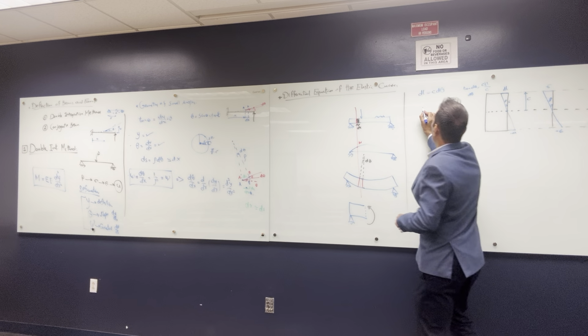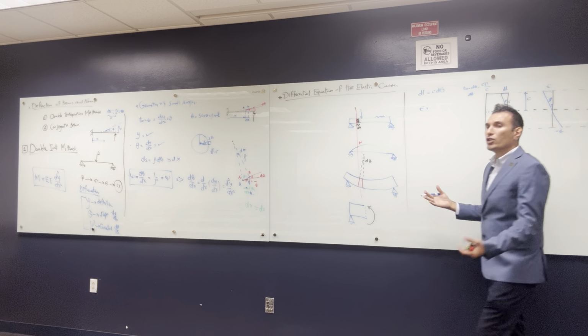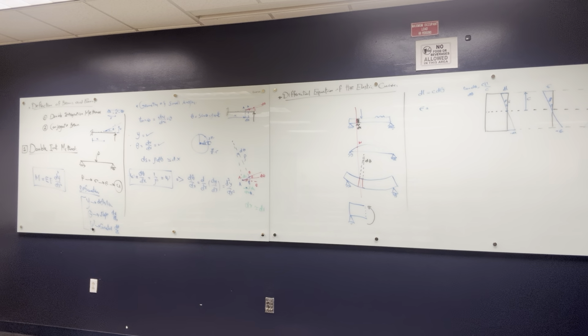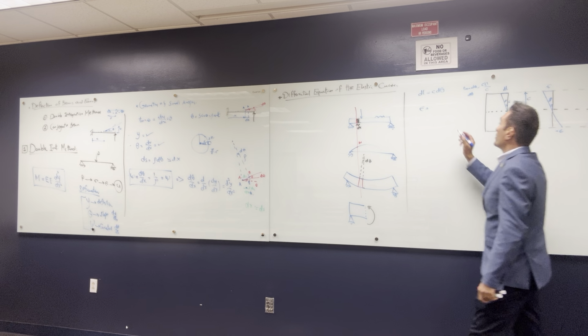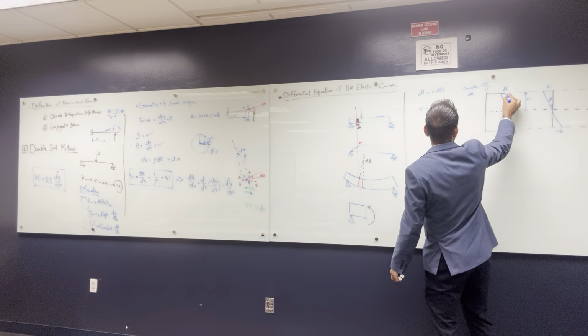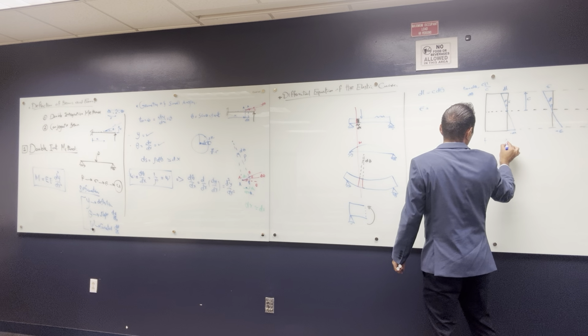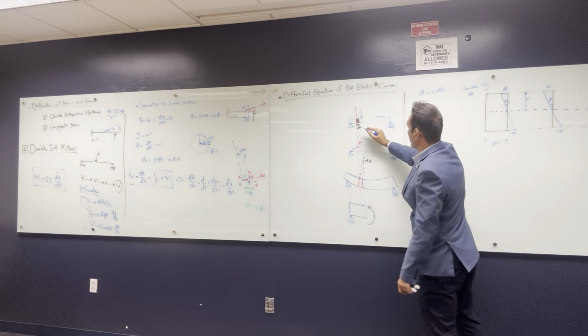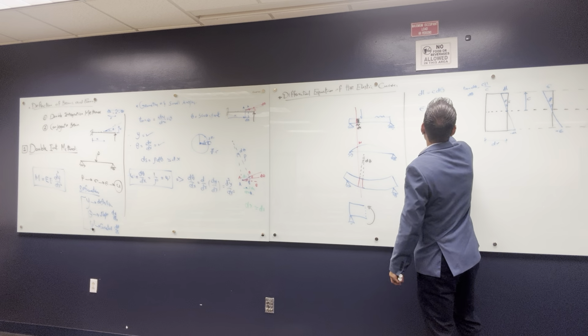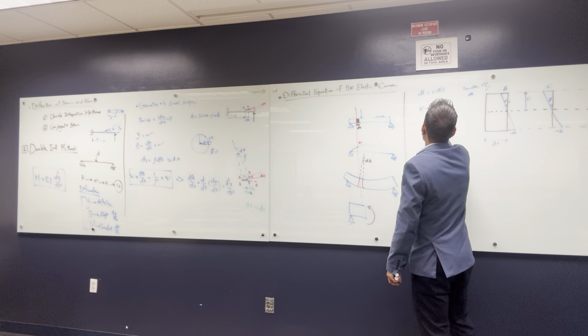Okay? So the strain, what is the general rule of the strain? What over what? The elongation over the original distance, right? Like if you pull this pin and this pin moved dl, but the original distance is L, so it's dl over the original length. So epsilon is dl, the amount of compression over this distance which is dx that we got. So it's gonna be dl over dx.